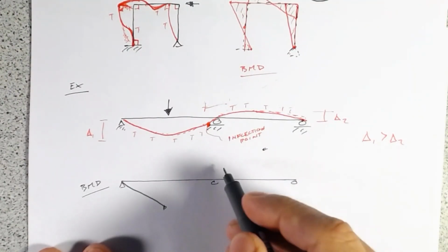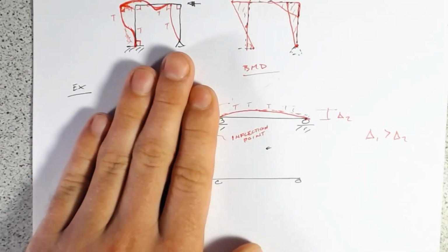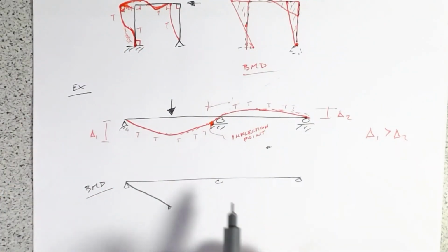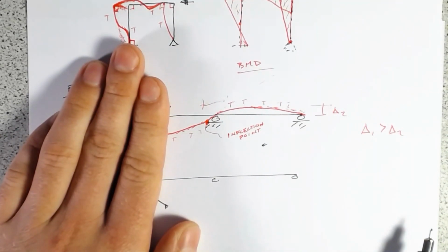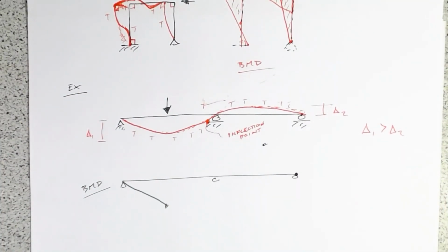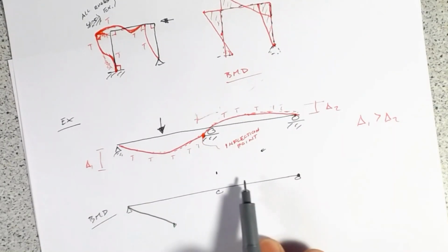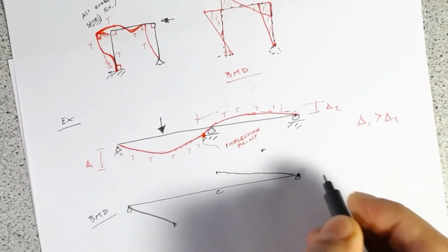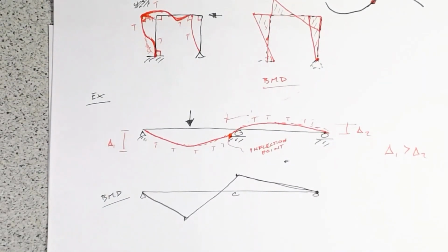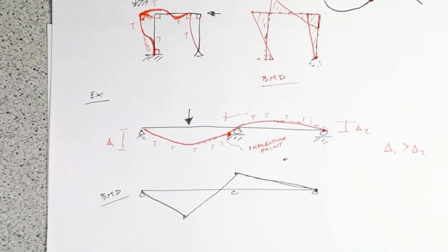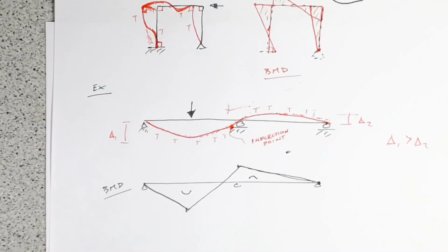Now, again, it's going to be linear here, but we've got to cross over at some point. And then we've got to think about what our span looks like over here. Well, over here, the only loading on this side is really just going to be the shear force from this reaction coming up. And we know that we've got a free end here, so the moment has to come back down to 0. That's going to be linear there because it's just going to be this shear force as we go through. And then we connect that up. Again, we've got a point of contraflexure. That's where our moment is going to be 0, and that's where we switch sides. So you can put your happy beam and your sad beam there as well.